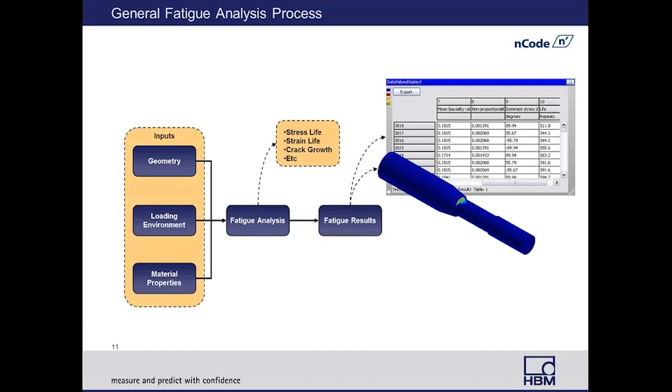If we're doing a DesignLife process, we may have some histograms or some XY displays if this is based off of measured strain gauge data. And we might also have some of our results summarized in the table. All of that, hopefully, if we're doing this correctly, going back to our inputs, where we may make changes to the geometry or the material properties to further optimize our design.